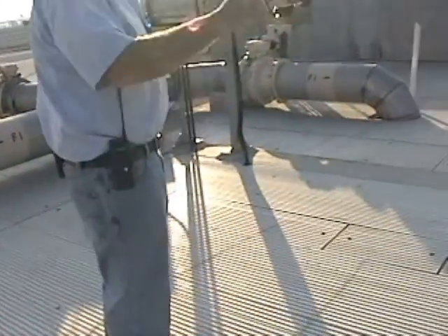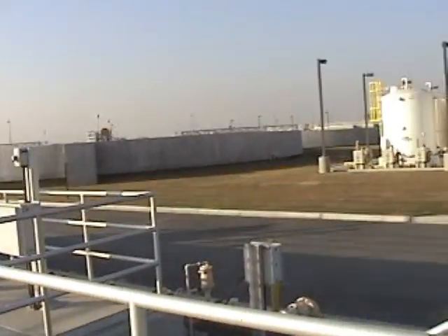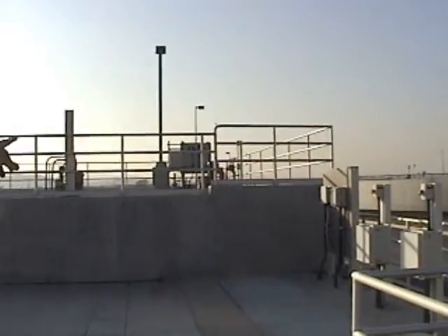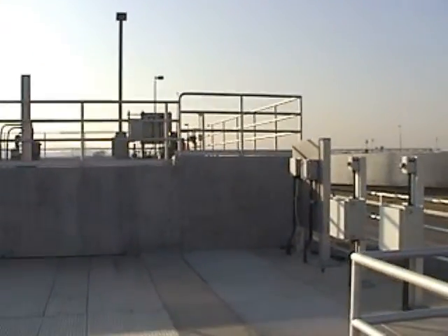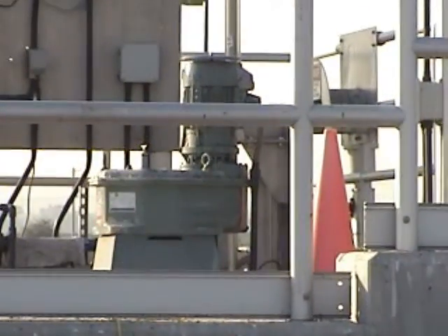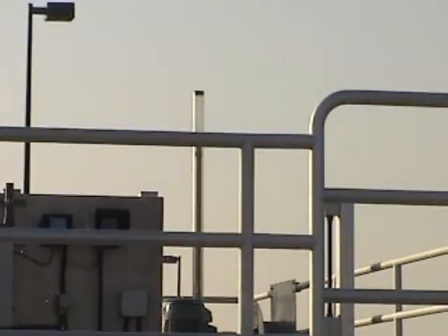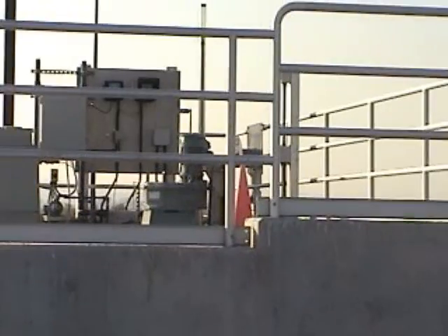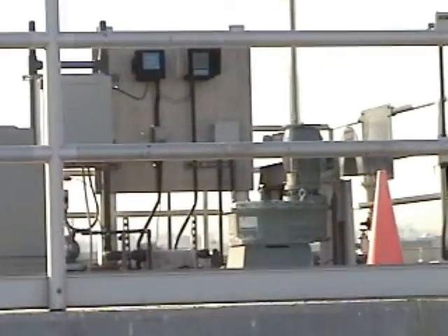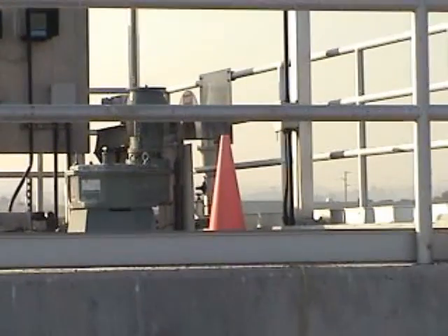The flow leaves a secondary clarifier through a common pipeline which enters the flock tank through that gate valve up there on the very top. You can see that rising stem right there. The flow enters the flock tank right there through these flock mixers where it's continuously running, and we're adding alum in there, and that is causing the particles to flock together.